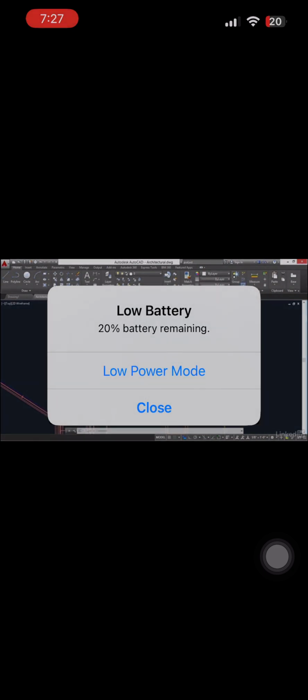In many situations, you'll want to move an object a measured distance. Let's say I want to move this lounge chair up 4 feet in the vertical direction. I'll type M, enter, click the chair. This time I'm going to right click, and it works just the same as the space bar or the Enter key. I'll specify some arbitrary base point by clicking somewhere on the screen. And I want to move this up vertically, so I'm going to turn on ortho. That's this mode right here.